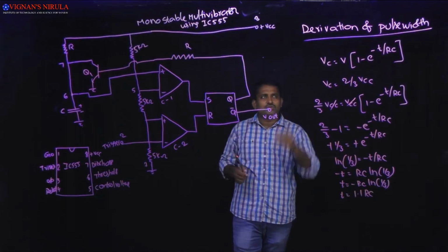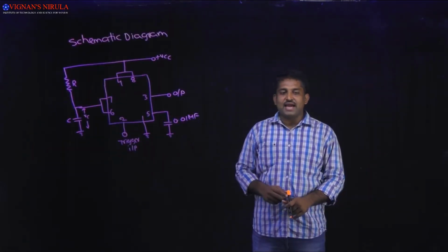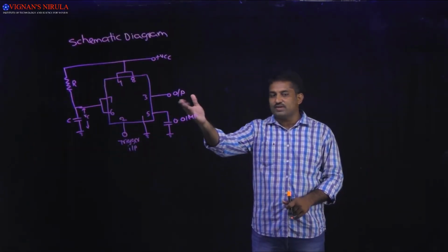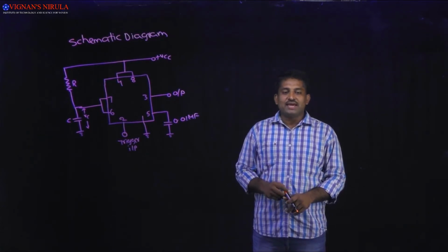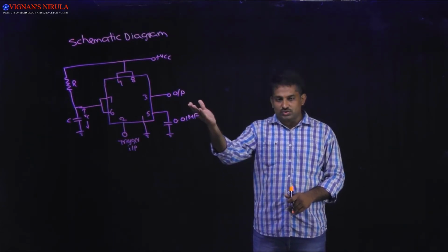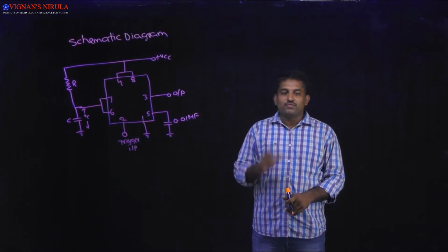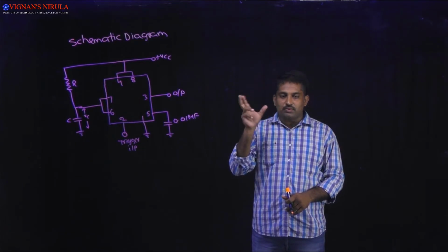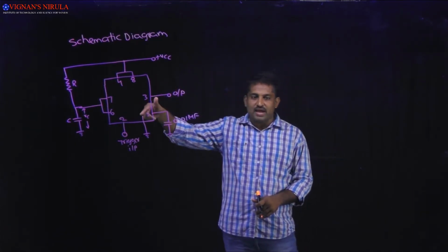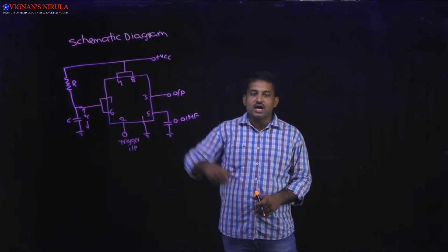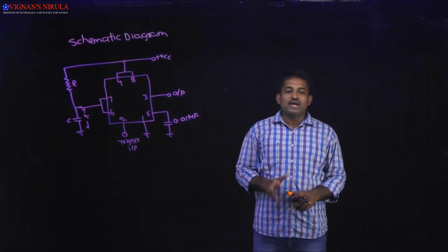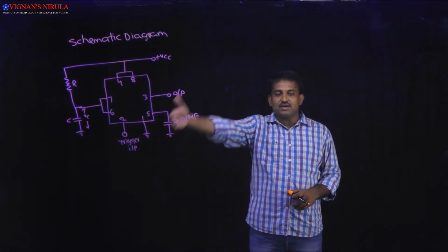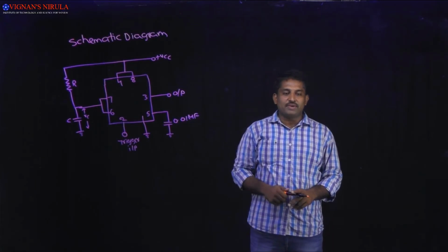This is about the derivation. The schematic diagram of IC555 is represented like this, which doesn't show flip-flops as well as comparators. If you are connecting resistors and capacitors external to this IC555, then it will be treated as a monostable multivibrator.